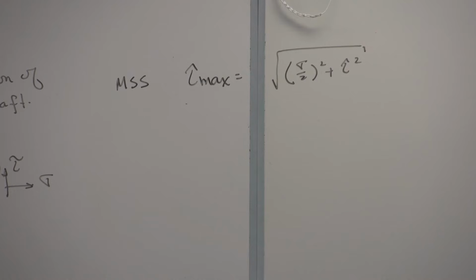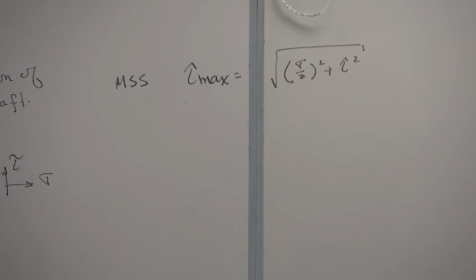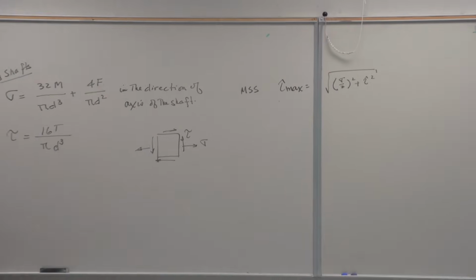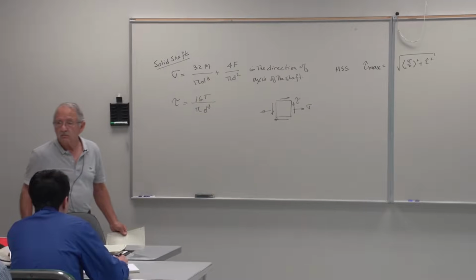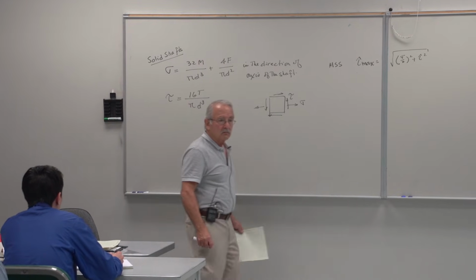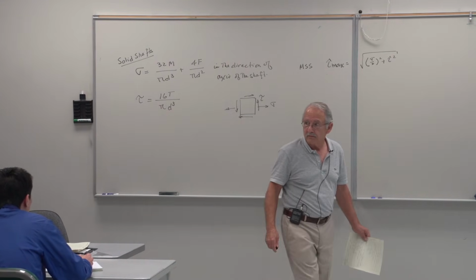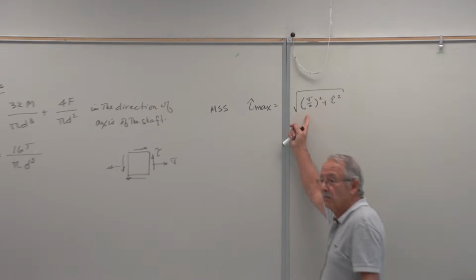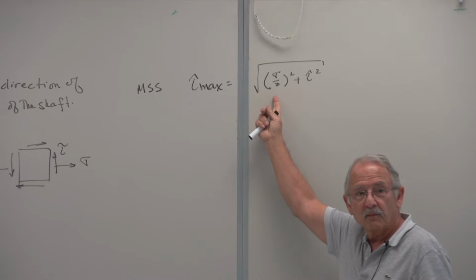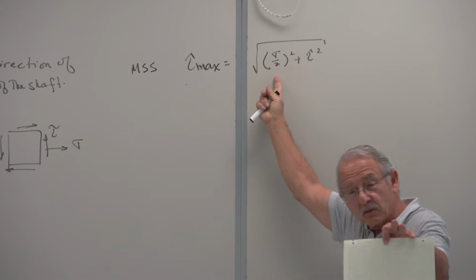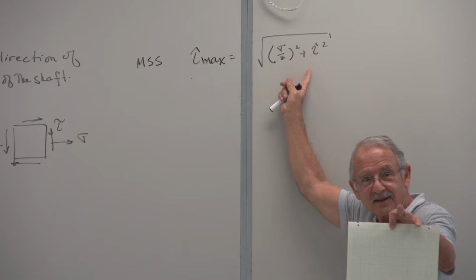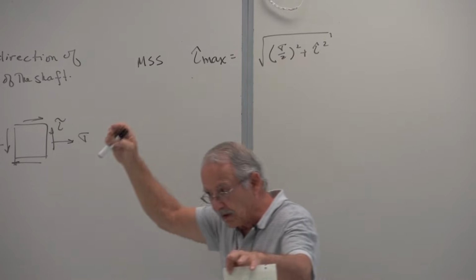Is this the maximum in-plane shear stress or the maximum of all shear stresses or both or neither? Do you know where this comes from? Both. Comes from where? This equation? Mohr circle. That's right. That's right.